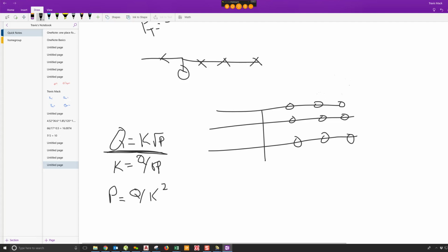Whenever we're trying to figure out the minimum flow coming out of a given sprinkler, we just take our area, which is often shown as A sub S, and multiply that by the density, which you'll often see as 0.1, 0.2, 0.15, whatever it is based on our hazard. And that is going to equal our Q, or our flow. Pretty simple. Area is square feet and density is GPM per square foot, so you come out with GPM, gallons per minute, as your units.